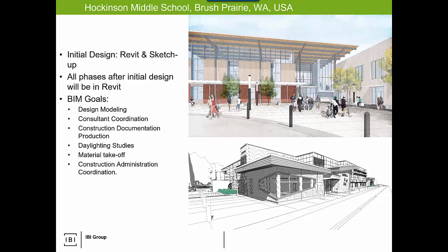The material takeoff was an interesting BIM goal, as well as daylight studies. That's an interesting one. It could be used for sustainability requirements. It could be used just to prove to the client that this is how we believe the light will filter into the building and where we will have potential areas of lower light or darkness. So very valuable. I hate calling these push button abilities, but a lot of BIM goals may not carry an extensive cost, but may bring a value either to the client or to another stakeholder.